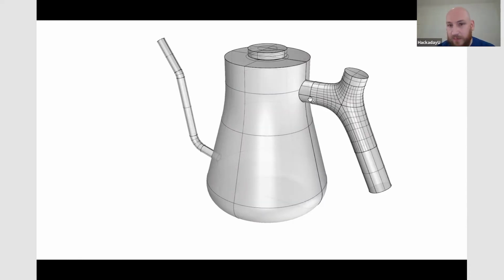Then if I do a split on the handle, so the handle currently just overreaches the interior. If I do a split, it's going to change that surface into a NURBS poly surface. And you can see how complicated that intersection is. That's why we didn't want to do it manually. And that's just trimming, because that's not a perfect circle, because it's going around the curved edge. The next thing I want to do in modeling this kettle is this has a cut